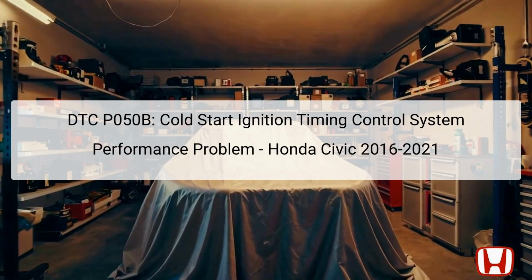The integration of various sensors, like the engine coolant temperature, ECT sensor, and the mass airflow, MAF sensor, and their accurate readings are crucial for the PCM to adjust ignition timing accordingly. If the ignition timing isn't appropriately adjusted, it can lead to poor engine performance, increased emissions, and potential engine damage over time.